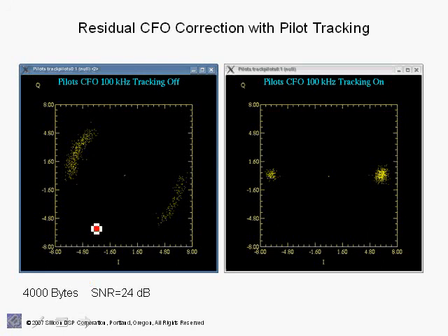And you can see that even though we are using both coarse and fine carrier frequency offset estimation, due to the large noise there is going to be a residual carrier offset, and if we don't do pilot tracking, then the pilots actually drift, as you can see here. They're actually rotated. As you can see, this will actually cause intercarrier interference and destroy the orthogonality of the OFDM carriers, and obviously the system would fail after a while.